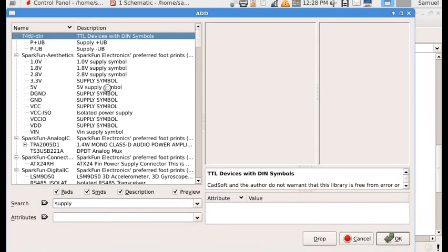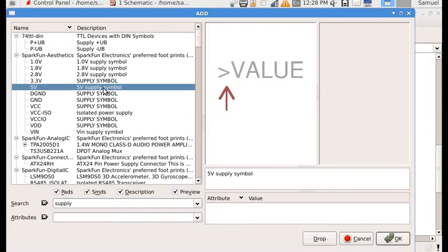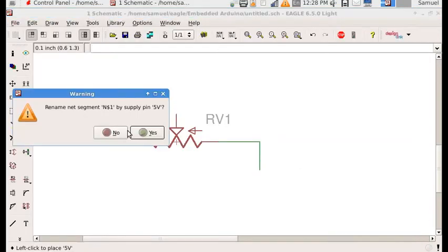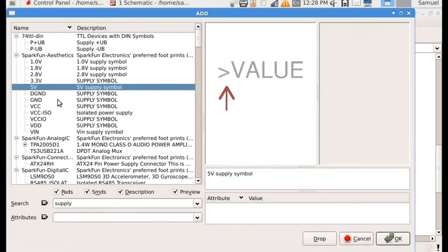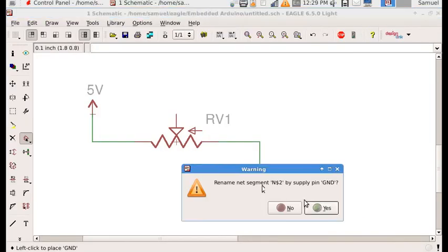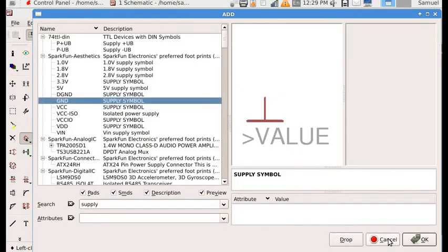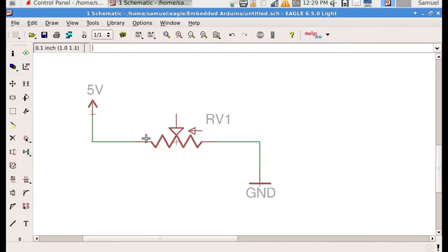We have one that way, one that way, we go here, a 5-volt supply, and we have a ground supply. Alright, so whenever you use the joystick, this is like when the joystick's in a neutral area. The arrow is right dead center on the resistor. Because a resistor resists current or resists electricity, you use it for passing through, but a potentiometer or a variable resistor makes it so you can move around this arrow on the symbol and it will change the resistance used and it'll change the voltage coming out of the right